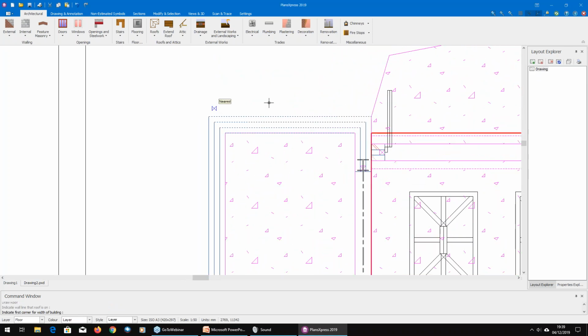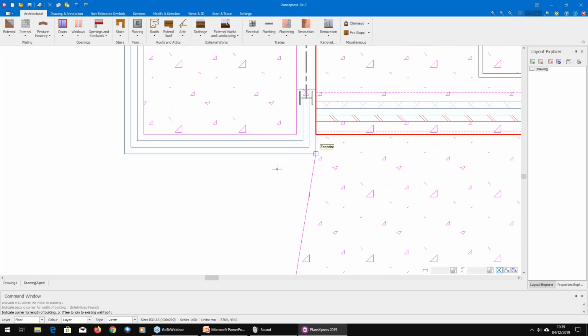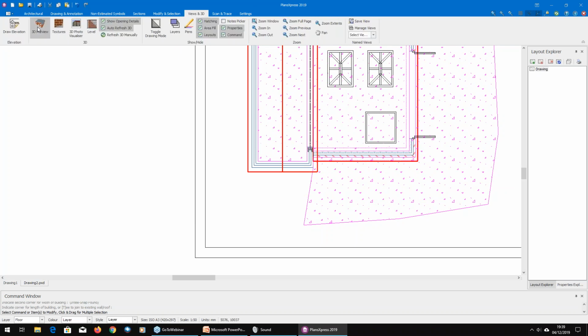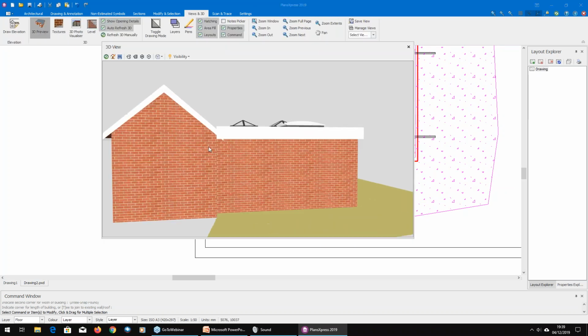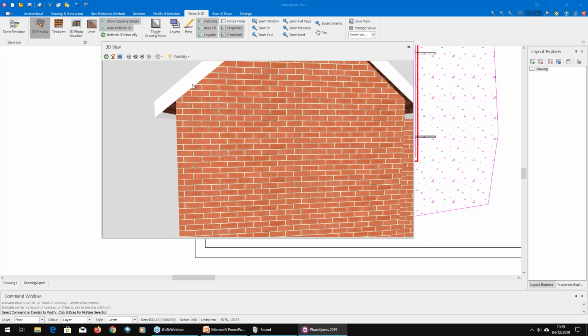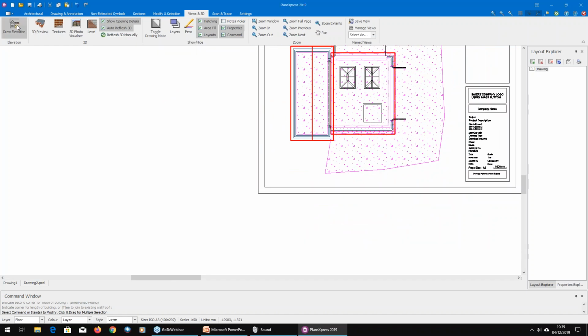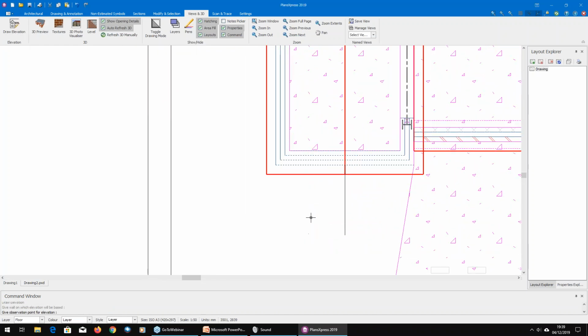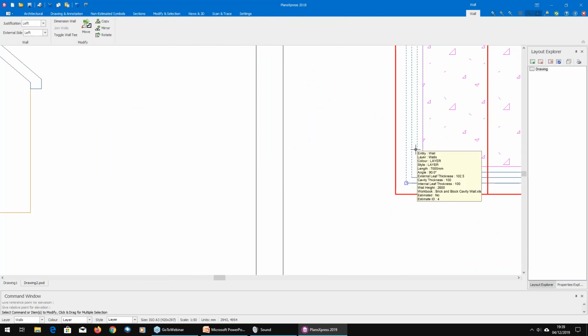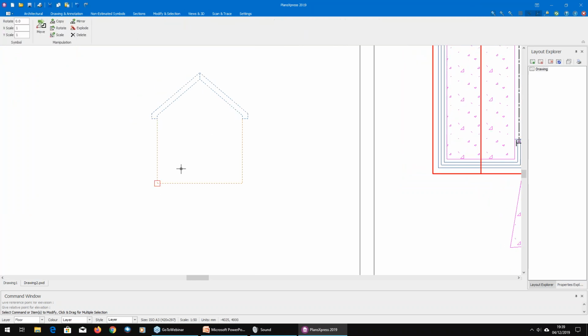So if I was to draw that in there, bring the 3D up so I can demonstrate, I might stretch that across. The internal skin is where the roof is going to be based on, and it cuts slightly on the external skin. When I demonstrate this, I take a quick elevation. I'm not going to include the flat roof as part of this. So that wall there is 2600. Just going to explode that one there.